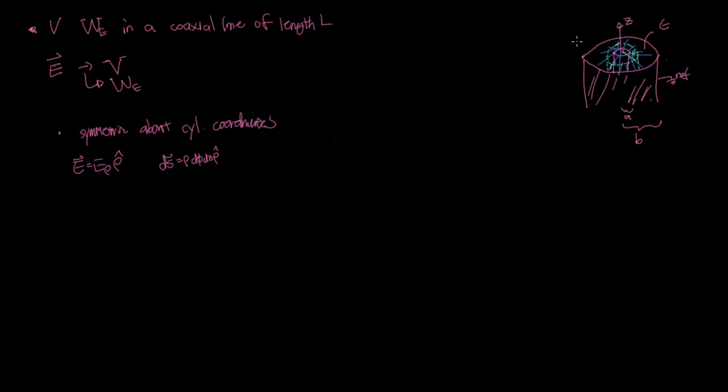So this is your dS, this is the function, and our electric field is going to be in the rho direction. In this case, one other piece of information, promise the last piece of information I forgot to give you in the beginning, is that you have a surface charge density along the surface of this inner conductor of rho s. And the total amount of charge enclosed for a length L will be rho s times the surface area of this conductor cylinder, right? So this is going to be a function of rho because the surface area of this enclosed surface gets larger as rho increases.